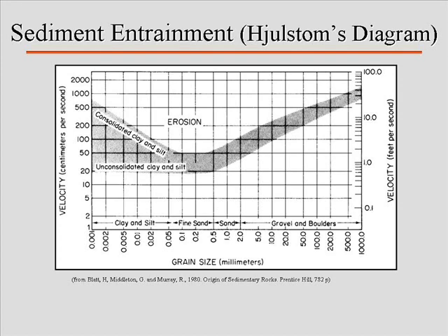Why? When you have superfine clays, don't they have an electrostatic charge? More or less, yeah. Exactly, right? Now, it says consolidated here. Consolidated is a term that can mean it's lithified. It's not lithified. We're not talking about actually moving shales or anything like that. But, as Kurt was saying, clay particles, which are platy, require more current to move them anyway because they don't have that liftability, but they also have a charged excess where you can have some things clinging together. In fact, this is one of the reasons why in some situations you will find very well sorted sand with big chunks of clay within them.